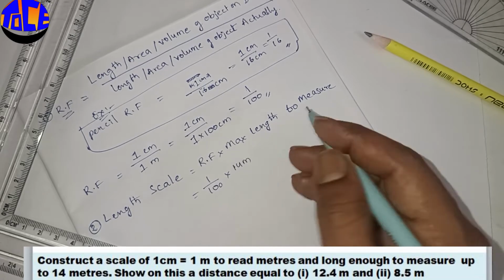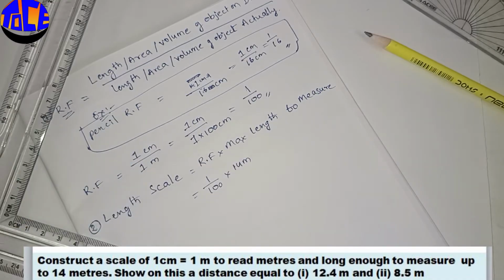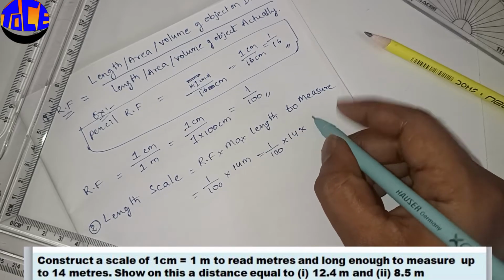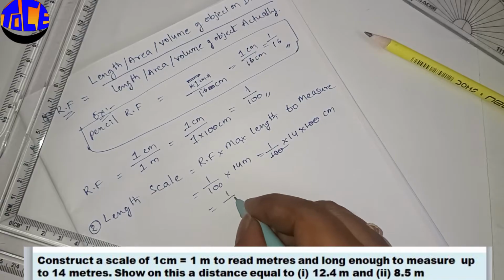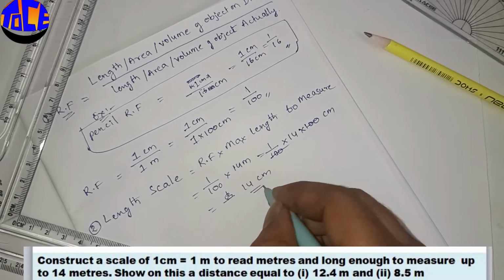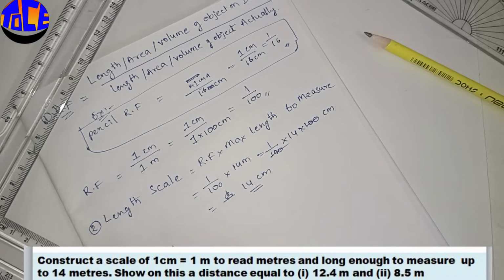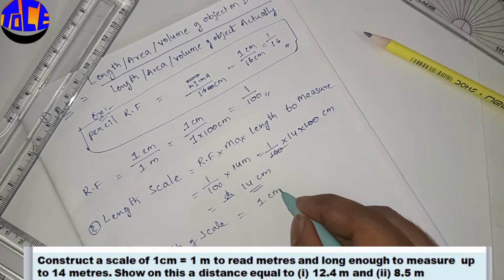So 14 meters is the maximum length, but here it is in meters, so we can't construct a scale in meters. That will be very difficult. So that's the reason, let us convert this into centimeters, so that it will be convenient for us to construct a scale in centimeters. So 1 divided by 100 is the RF value, and 14 is in meters. To convert into centimeters, we'll multiply with 100. So 100 gets cancelled, and it will be 14 centimeters. So now my scale length is 14 centimeters. Then what will be the width? The width of the scale you can take approximately 1 centimeter.